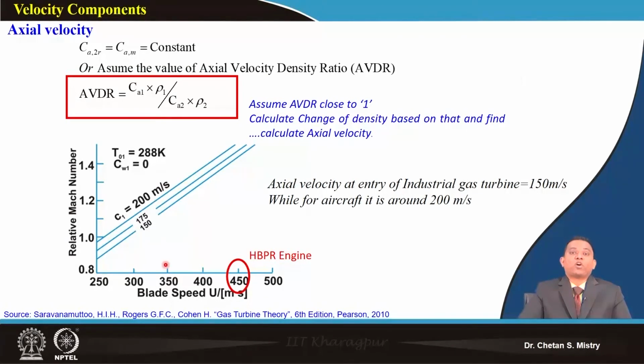So the selection of the parameter called flow coefficient comes into the picture when we are deciding this. When we are not aware of what all parameters are known to me, say my mass flow rate is unknown, I don't know my peripheral speed, I don't know my axial speed, under that condition you can safely assume the flow coefficient in the particular range as we have discussed, and then after you can start doing your design. Okay, so there are strategies for the selection of this parameter.